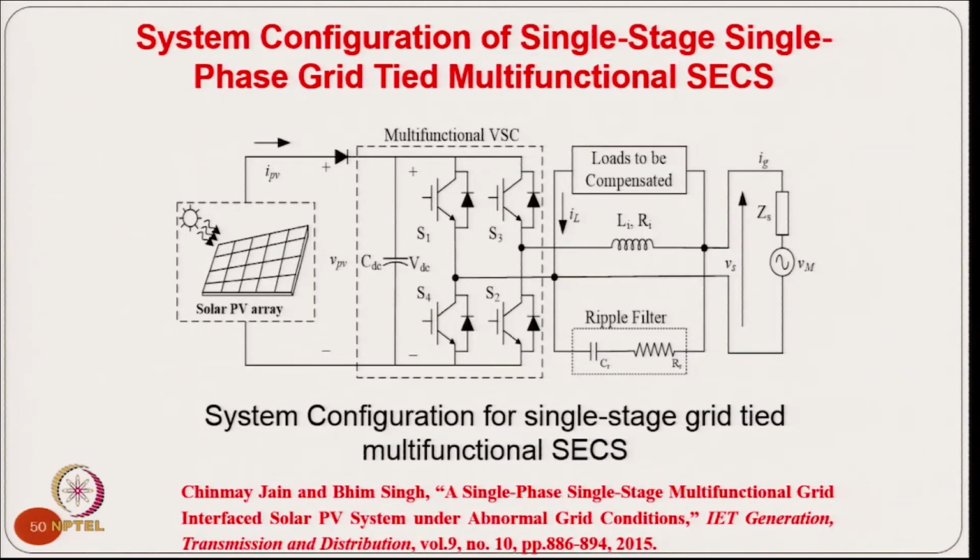Now, coming to this single stage system, can we do load compensation? Yes, you can do the load compensation utilizing the inverter. Now, the inverter is doing MPPT, and it is also compensating the local load and feeding sinusoidal current to the grid after feeding the local load.